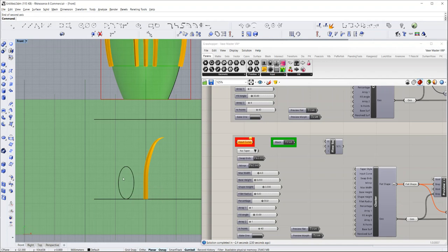and we've drawn it. Now, to save some calc time, we've got to kind of look at this. I said that this was 90 degrees from here to here, so this is sitting at 45. If I move this right to here, it'll be in between these elements. So let's try that and see what happens. So I'll select my move, select this point and the intersection there, and we'll give this a shot.